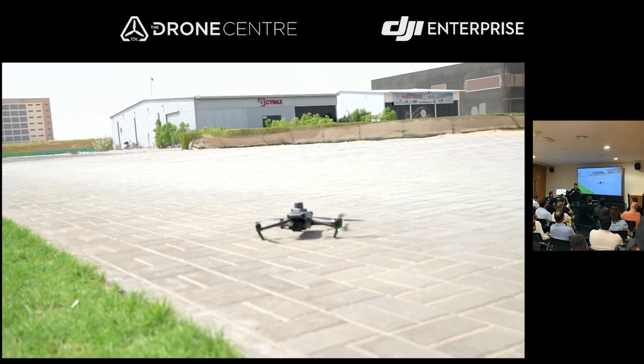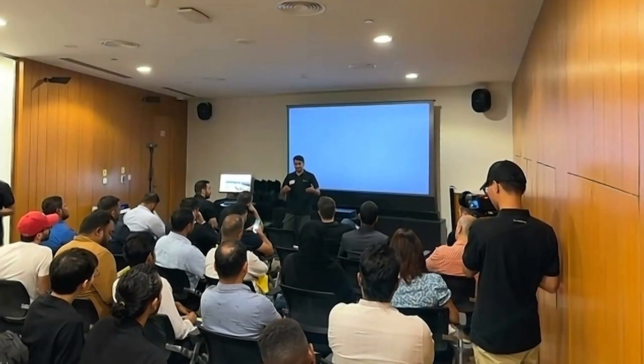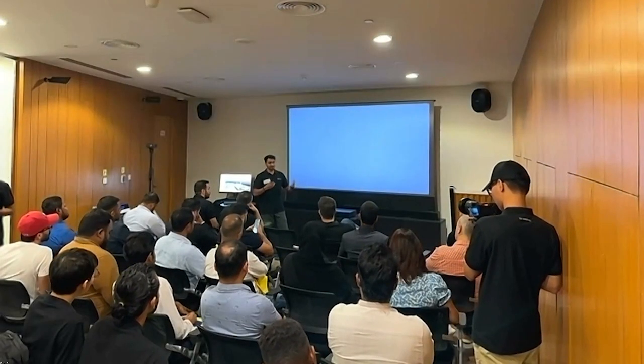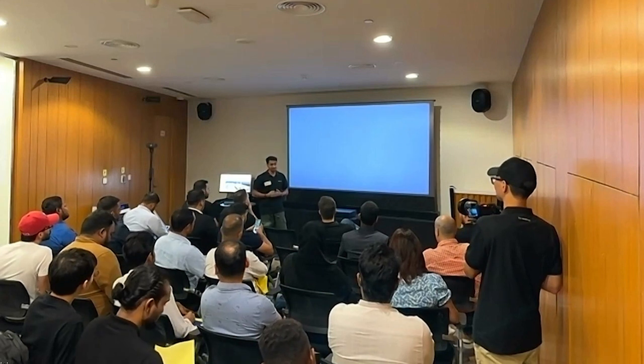So it's a straightforward process from setting up the drone and connecting the drone to the controller, and setting up your DRTK base station, and using the specified point of your work. Once you have everything, the data will be taken by an SD card, and you can use either DJI Terra software or any third party like Pix4D or Agisoft software to process the data, and you are ready to go. So this is a simple process when comparing to your other surveying work.